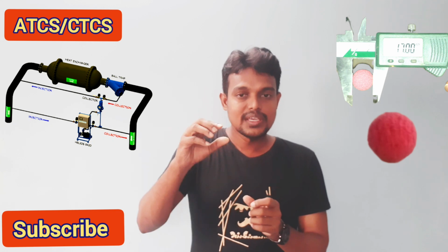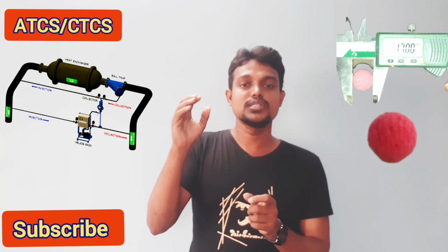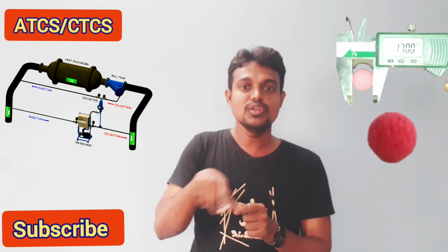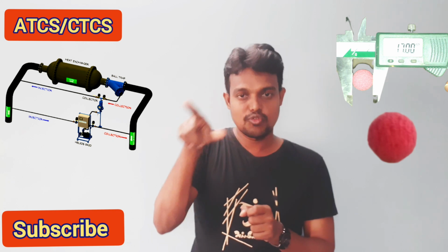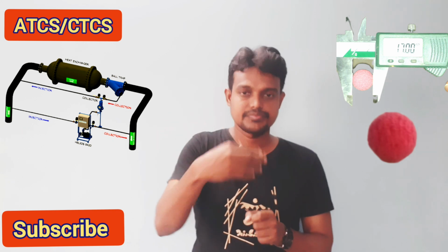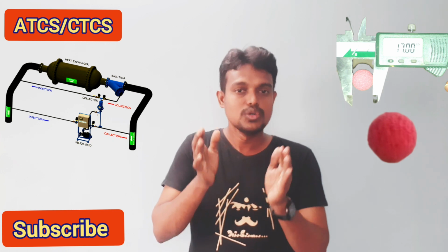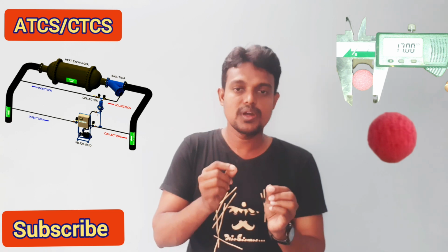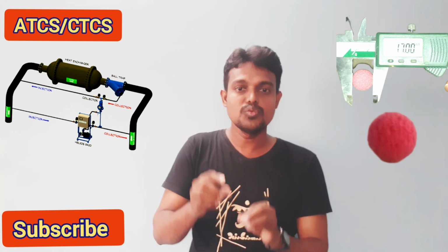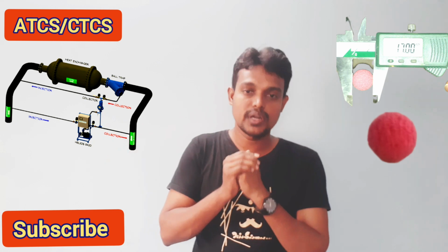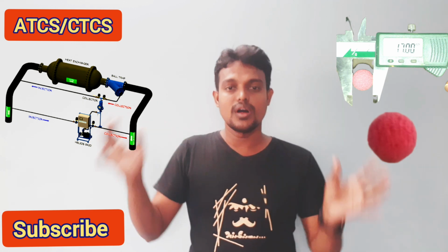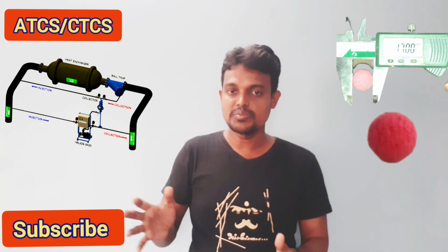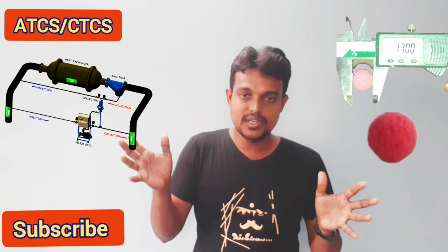Why? Because, as I told, if it is very small compared with the condenser tube coil size, your system will not effectively remove the scaling which forms inside the condenser coil. So once in 1000 cycles, you have to take out your sponge ball and measure it, and if it is more than 1 mm less than the original size, you need to remove all the balls.